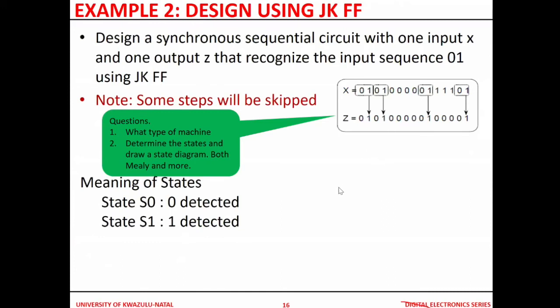Okay, people are done with the diagram. Those ones who are done, you should have gotten something like that. Two states. I told you the easiest way. The first thing, these are what we call sequence recognizers. It's a group of machines that recognize. Sequence recognizers go for the right thing. Say 0 detected, 1, you go to 1, that is 1 detected. That is the right combination you need. And then fill in the dots.